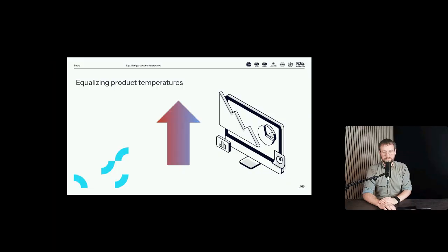But there are other things that come into play as well, such as sensor performance, the sensor you're using, and how fast does that respond to temperature changes. So definitely is one of those key elements to be aware of. But as a rule of thumb, again, I would always advise on just choosing 5 minutes and below. It's very rare that isn't sufficient. But thank you very much.